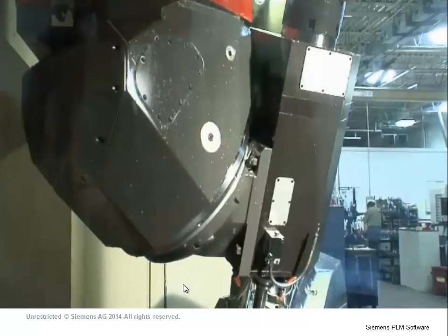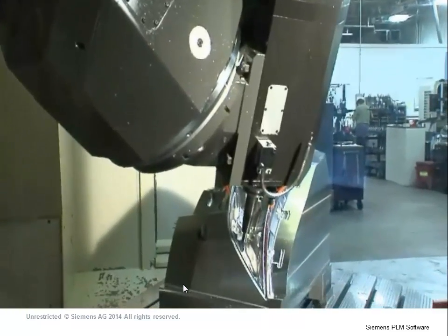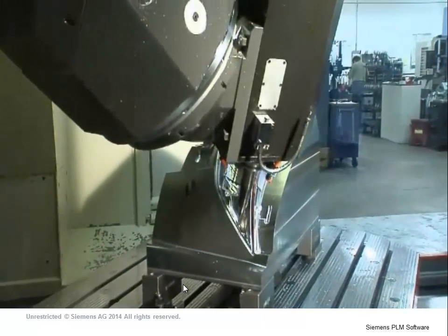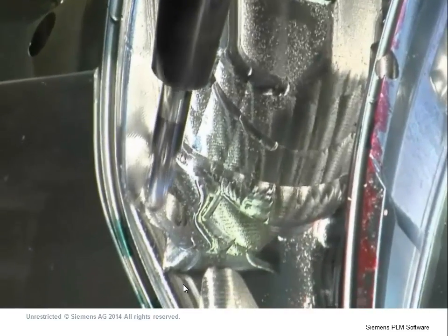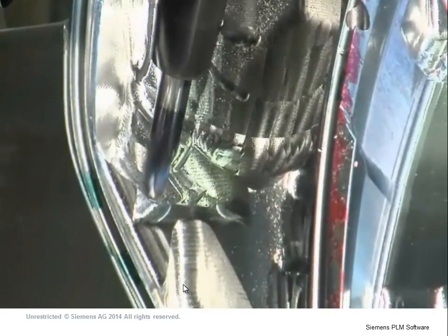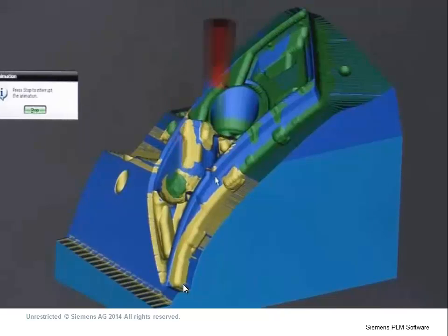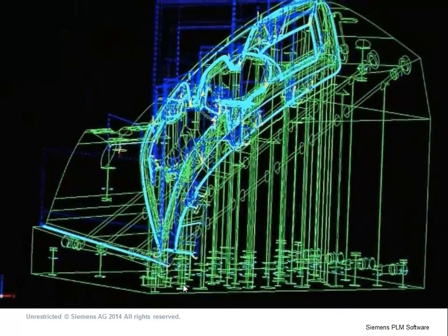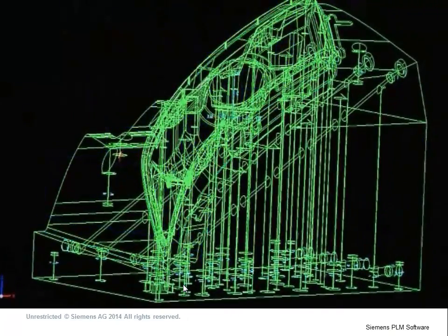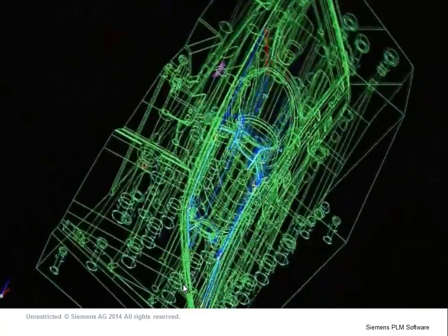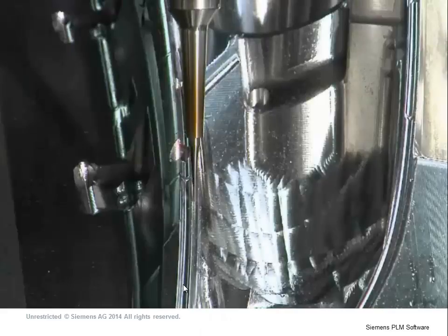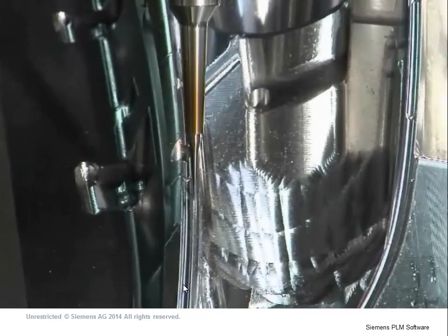You've got to save time, you've got to save money, so we implement high-speed machining whenever possible: small cuts, light cuts at fast feed rates. And yes, NX has several options that you can adjust your paths accordingly. There's options in NX that'll actually turn the corners, which creates a much nicer and smoother path. It doesn't have the jerkiness of the machine. It's faster, it's better quality. Now you just set it up and away you go.